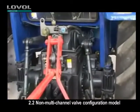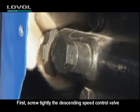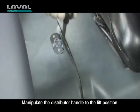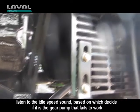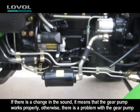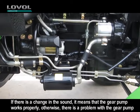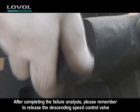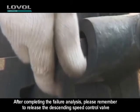2.2 Non-multi-channel valve configuration model. First, screw tightly the descending speed control valve. Manipulate the distributor handle to the lift position. Listen to the idle speed sound, based on which decide if the gear pump fails. If there is a change in the sound, the gear pump works properly, otherwise, there is a problem with the gear pump. After completing the failure analysis, please remember to release the descending speed control valve.